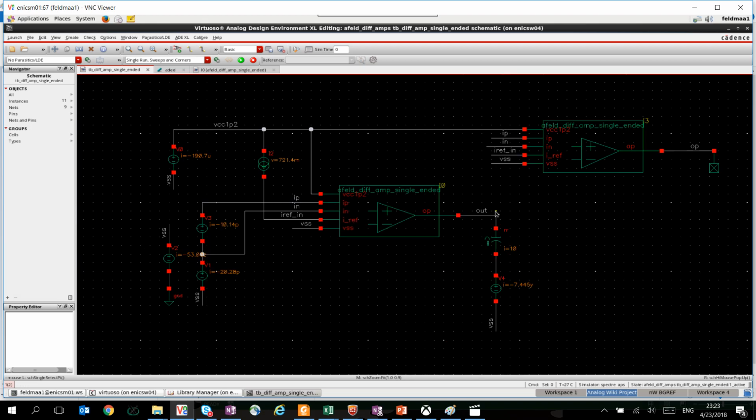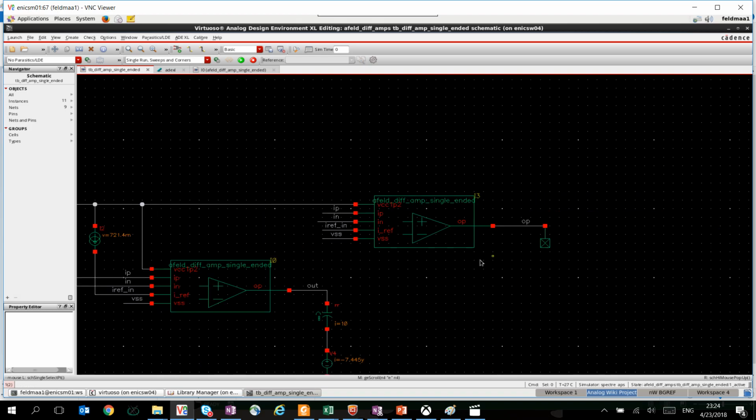So what we're going to achieve by doing this is, once on the left side we have a DC, this output is going to stabilize in its operation point on the graph that we've shown of I out over V out. And then we're going to apply the difference around that point when the inputs are constant, and that's how we're going to measure R out. So this is our circuit. On the top right side over here, we just have the same circuit where we're going to measure the open loop gain of this circuit.